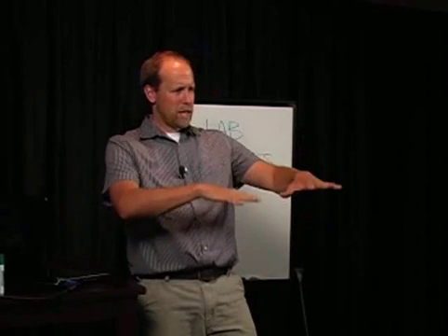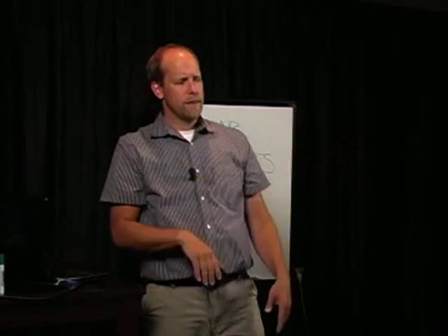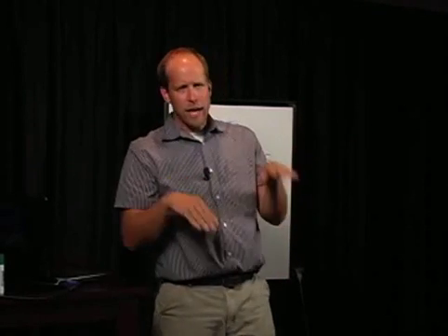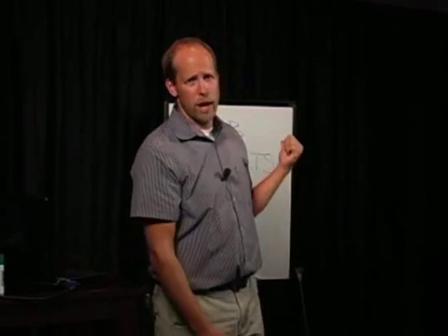Don't step on the carpet. The carpet ideally would start to float up. It'll bubble up and down and wave. Try to blow above the padding and then lift the padding and try to go under the padding. And get multiple fans. One usually doesn't cut it, because when you're trying to dry out one area, you're leaving the other wet areas behind. So you have to dry it out quickly. And it really works.